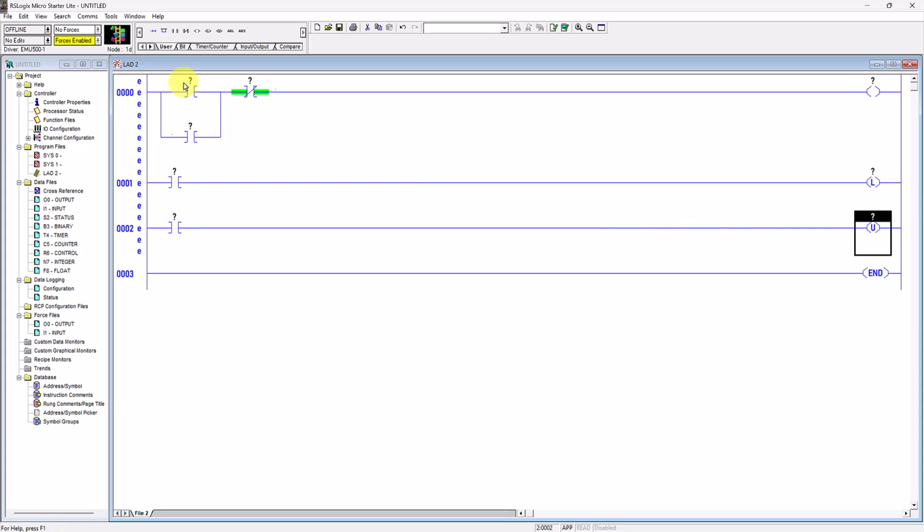All right, so in order to write the addressing for each instruction, there are a few methods. The traditional method is you double click and you can write it yourself. Let's say digital input column, okay, slot 0, okay, dot word 0. This is word 0. It can be word 0, word 1, word 2, word 3, depends on your PLC digital input. Word consists of 16 bits. Alright, then slash. Anything followed by slash is bits.